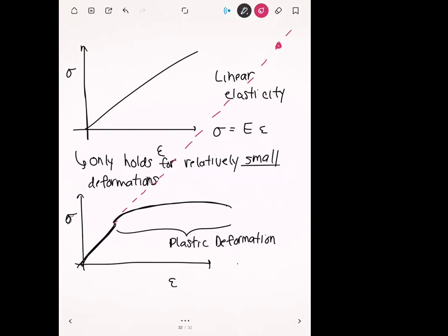And so if you're pretty confident on all the other settings of your simulation, I'd say go for it. But a lot of times when you're running finite elements, you're tinkering with things a lot. You're tinkering with the mesh, you're tinkering with the boundary conditions. And if you have to wait even 3 or 4 minutes for each simulation because you're trying plastic deformation, that's going to add a lot of time onto your whole analysis. And so you kind of have to be careful of doing that. But if you have a lot of confidence in all the other settings being right, I'd say go for it.